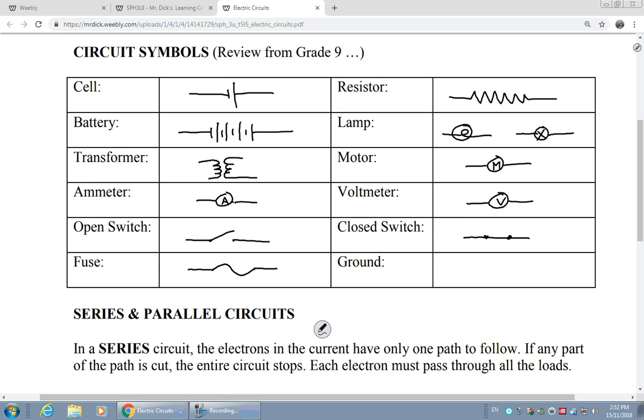And so that fuse was something that was used to break first so that it didn't melt anything further from there. We now use more advanced technologies in a lot of cases and use circuit breakers, but it's the same basic idea. It's something that is meant to be triggered by high amounts of current, and it will automatically break the circuit when the current gets too high. But with circuit breakers, there's also a button feature that will allow you to reset it. Whereas with fuses, it's actually a piece of metal that melts, and so they need to be replaced. But either way, whether it's a fuse or a circuit breaker, we tend to represent it with that same symbol that we would use for a fuse.